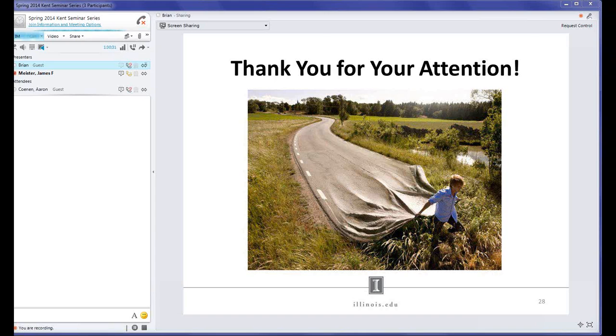Perfect. No, because that's something that, to be honest, with Hyunwook Kim's work, people just always questioned it. And we're wondering, can we run some of those tests? There are some pull-off tests that people have done at like University of Nebraska-Lincoln, but they do all their discrete element modeling mainly at higher temperatures. So when they run it at 25C, maybe those pull-off tests are a little bit better, but when we start to get down to -12, those pull-off tests really are just measuring a strength, and you're not going to get any displacement. So is that really applicable in this case?